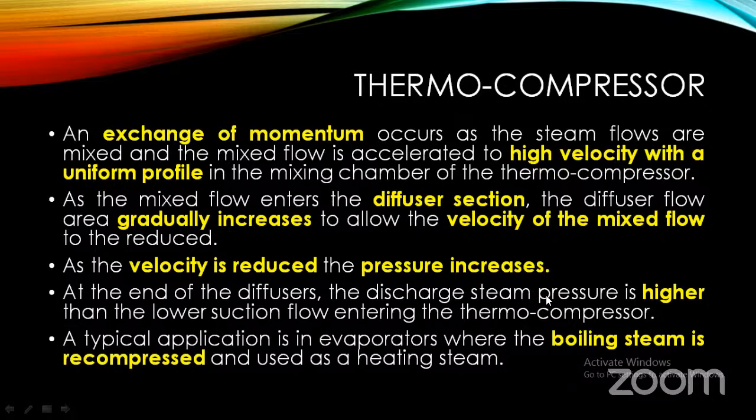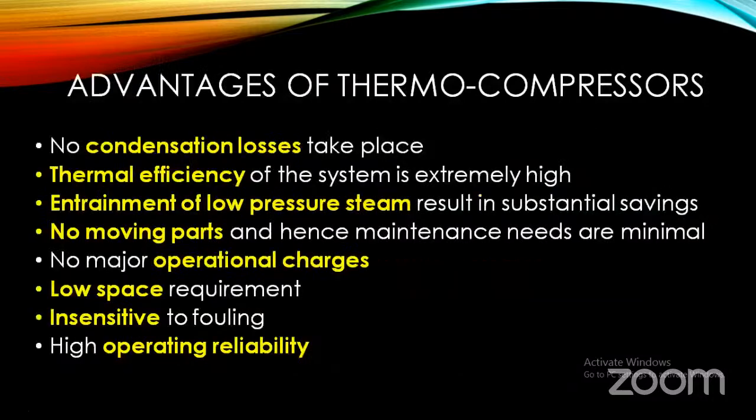It may be asked as a 2 marks question or 1 mark. So what are the advantages of thermocompressors? Here, there won't be any condensation loss, because there won't be any sudden conversion of higher pressure to lower pressure. So those losses will not be there. And since we are mixing, waste heat recovery is there, thereby the thermal efficiency will be higher. So there will be some savings in the system.